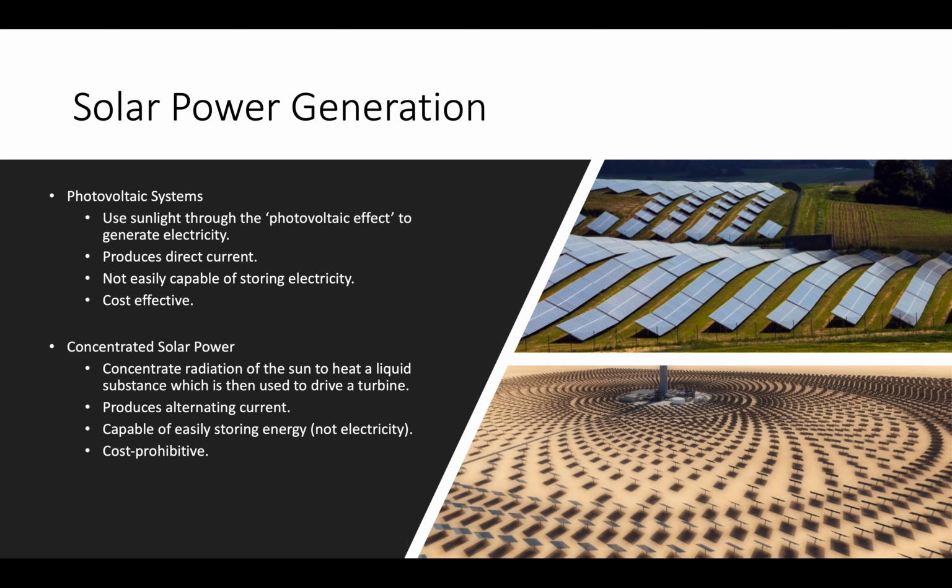So let's talk a little bit about CSP, concentrated solar power, versus photovoltaics and their energy storage and efficiency. CSP systems are capable of storing energy by the use of thermal energy storage technologies and using it at times of low or no sunlight, like on a cloudy day or overnight, to generate electric power. This capability increases the penetration of solar thermal technologies like CSP in the power generation industry because it helps overcome intermittency problems. It helps overcome issues about not getting electricity when the sun isn't shining.